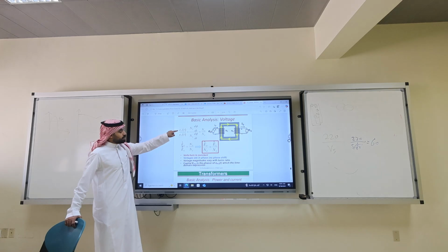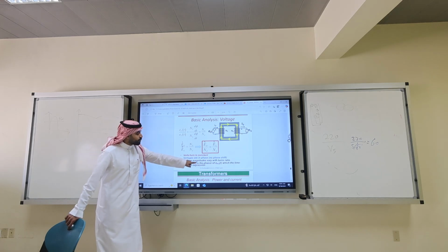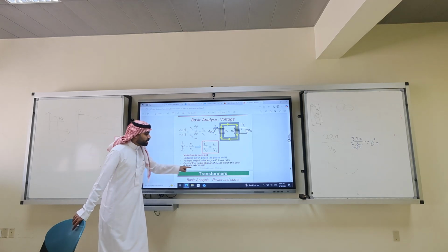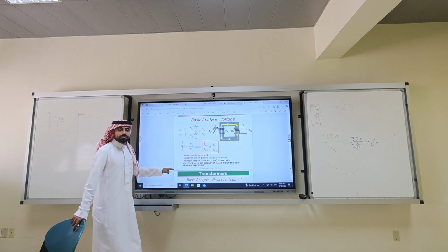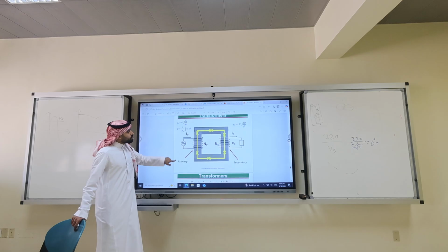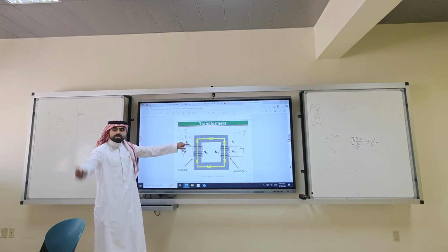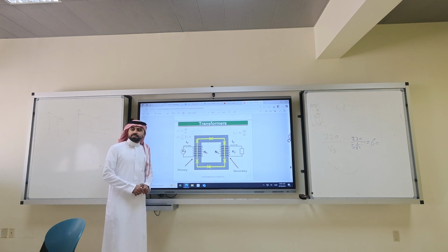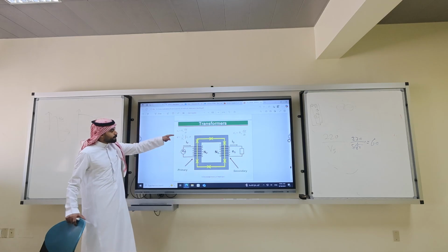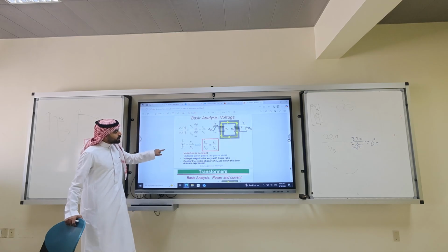Why small e we say? Because capital E is for phasor, small e is for time domain. This expression is made for time domain. Why? Because integration is a function of time domain. You don't want to do integration with phasors. Have you ever seen integrations with phasors? No. It's too much, right? It's too much simplification and too much complication. So don't do it. So that's why we use a time domain.